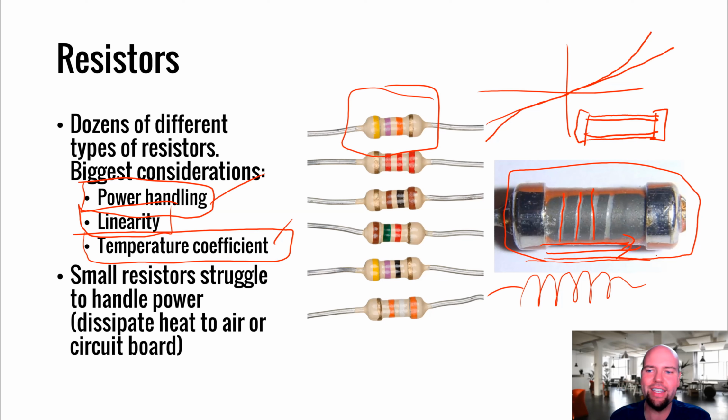These things cost a tenth of a penny a piece, so it's not like you have somebody putting this thing in a spinning machine and running a little tool across it. They're typically done with lasers, and they're done at extremely high speed. They crank through a million of these resistors a minute. After they cut them, they measure them, and a robot puts them in the proper bin based on the precision and the measured value, and then they paint them, and we'll talk about this paint color a little bit later. But yeah, that's how they make it. I've always found it's really neat how they make resistors.